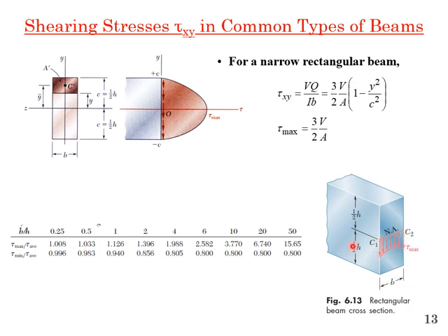It will be maximum at the neutral axis, but as the ratio of b by h changes, the shear stress distribution will also change. So if it's 0.25, meaning the width of the beam is very small with respect to the depth of the beam, the maximum shear stress is close to the average shear stress. At 0.5 it will be the same. At 1, we can consider it almost equal, but when the width of the beam increases, this ratio changes.